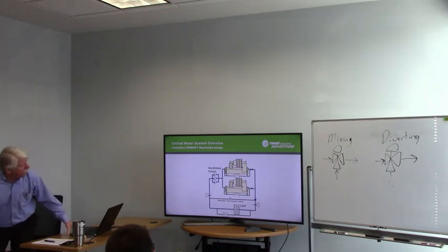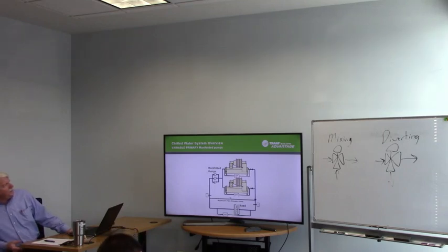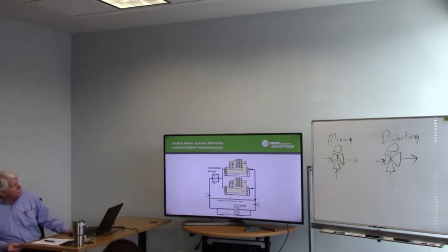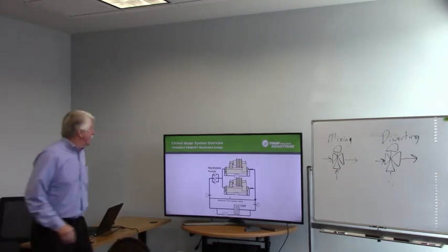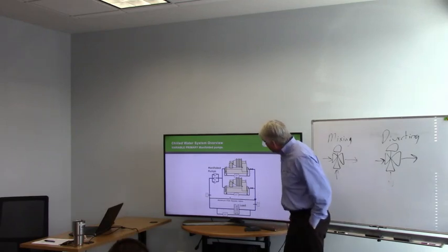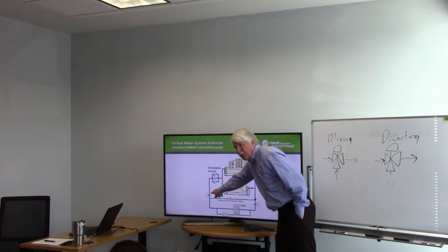So now, we have manifolded pumps. Now this is getting into chiller sequencing, when we're talking about the chiller sequencing application program and how it works. The first thing that becomes extremely important is the location of your temperature sensors. Now I'm showing it with a supply air temperature here and a return temperature here.